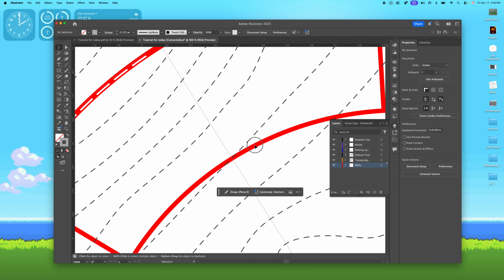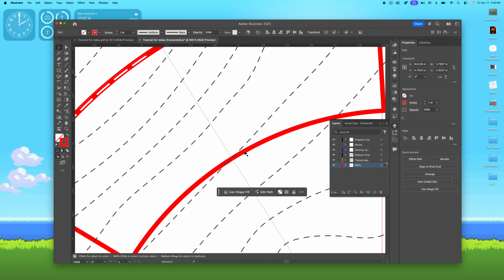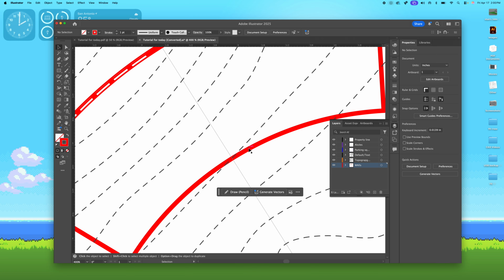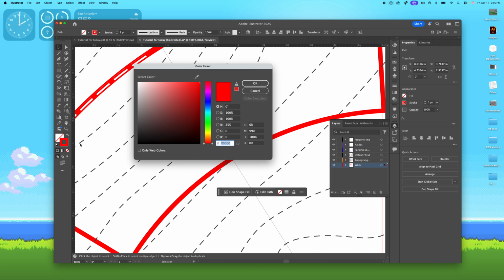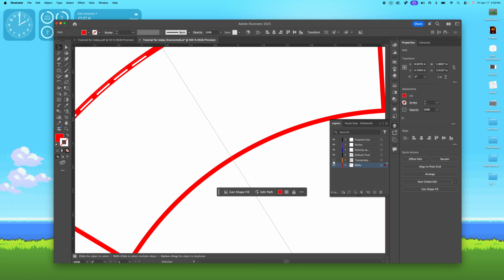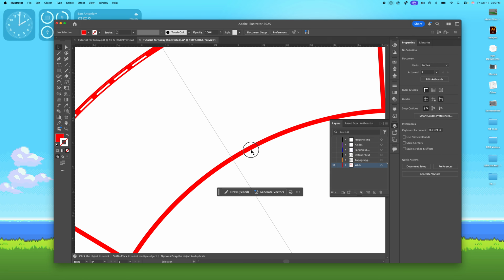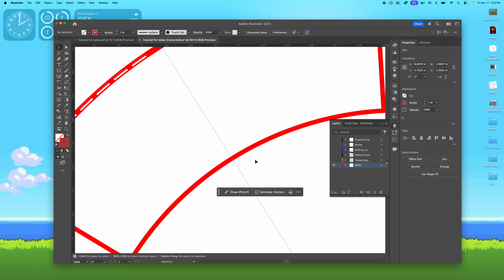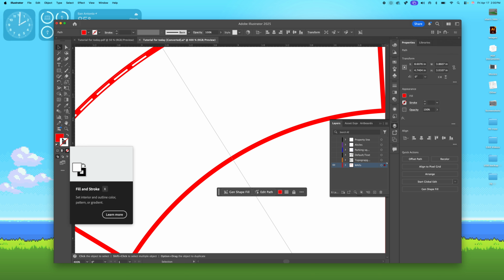In my case, you'll notice that when you click on the hatch, excuse me, it comes in as a fill, right? So you can take that piece and of course start to fill it. Now in my case, it looks like I accidentally clicked on the other piece, so I may actually want to even isolate it and find out what that is. Oops, I accidentally put it all in the walls layer. So I might have to click on it one at a time. So there it is. There's that fill versus the stroke.